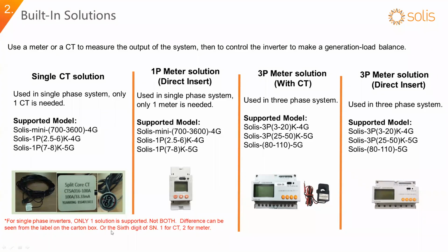And one thing to mention is that for the single phase inverters, we have different models. One is the CT model, one is the meter model. So if you ordered a CT model, then you can only use the CT solution. And if you order a meter model, then you can only use the meter solution. Those cannot be mixed up.